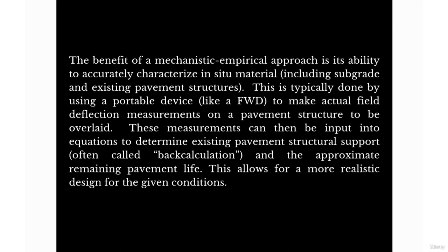If the contractor fails to perform on site and you designed your design to last for a certain amount of time and it fails, then you can go back and the contractor has to be accountable because they did not meet your design requirements. Of course, like with everything, there's a certain minimum amount of tolerance, and you must put that in your specification, and make sure that there are certain things that the engineer needs to sign off. For example, the existing ground California bearing ratio, you need to make sure that it is as you designed it for.